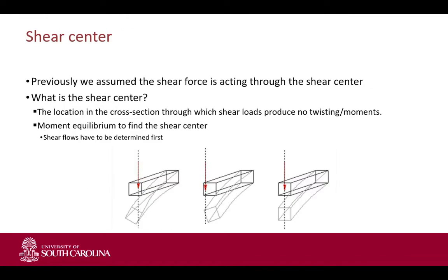Yeah, we said the shear center is basically the location at which we can apply a force, and then our structure purely bends, and we don't see any twisting or coupling between twisting and bending. What we do to find that shear center, for a symmetrical beam, especially when it's doubly symmetric, it's easy to find because it's located at the intersection of the two axes of symmetry. But then you have to have two axes of symmetry.